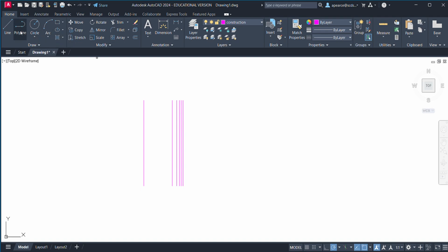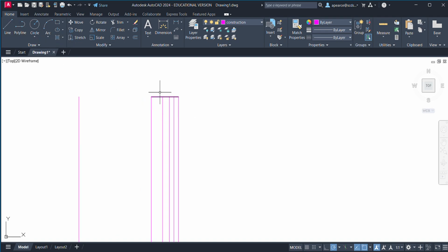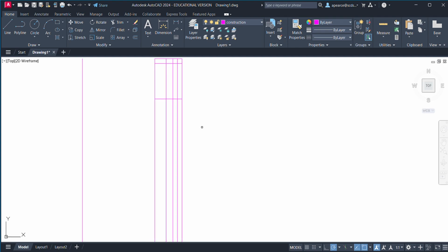The next step, we're going to draw a line from the top straight across, and we're going to go to offset, and we're going to offset this one down too. Now, once again, these numbers come right off of the drawing. So after this 2, we're going to offset down 15 units right here, and then offset 4 2 times. So down 4, then down 4.